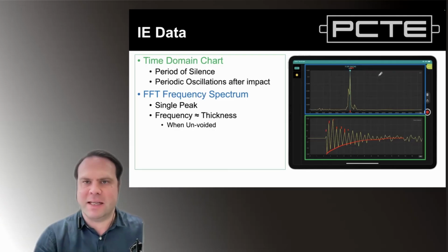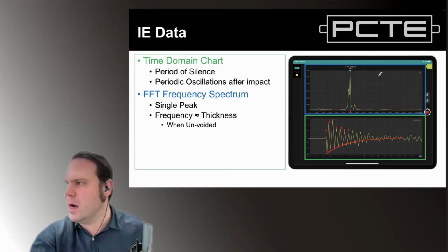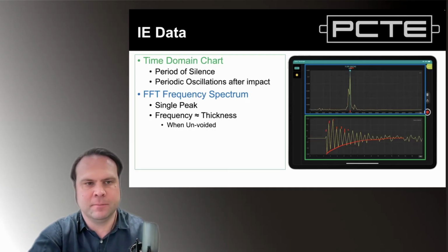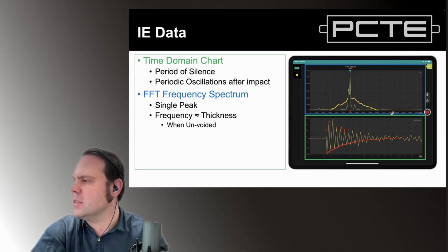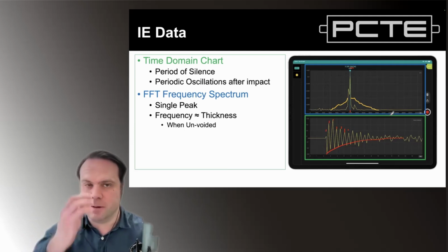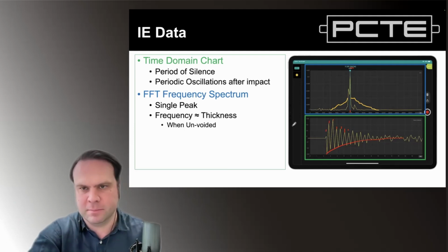You'll find that real impact echo results are perhaps not quite as clean. They may have, just because reality is a little bit less tidy, sort of a mountainous shape where there's signal frequency energy before and after, but there's still a clear signal peak elsewhere on that chart.